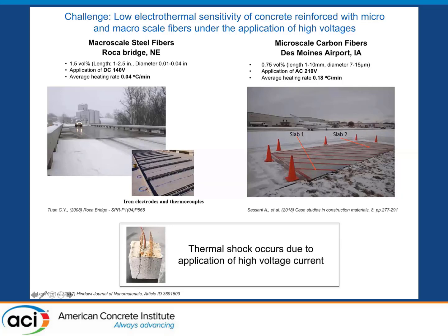We have found 2 cases reported in the literature so far. The steel fiber reinforced concrete overlay on the deck of the Rochester Bridge over the Salt Creek at Lincoln, Nebraska, was the first implementation using conductive cementitious materials for de-icing. We show this in the figure on the left side of this slide. The authors reported with the application of 140 volts direct current, the conductive concrete exhibited an average heating rate of 0.04 Celsius degrees per minute, which is kind of low.